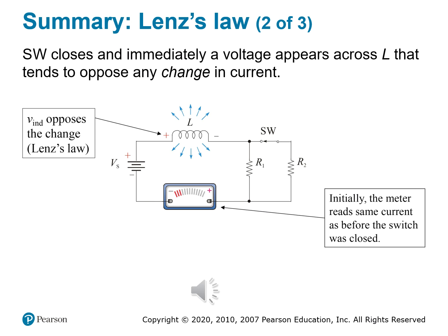The induced voltage opposes the cause of the flux change, and so in this case, the surge in the current. That's why the meter initially reads the same current, even though the circuit path has changed. The current doesn't jump instantly. I'll remind you again, think of it like electrical inertia. A coil wants the current to ramp up slowly. It generates a reverse voltage to delay that increase, and eventually the inductor settles and the current rises, but not without a fight. This behavior explains voltage spikes when you open a coil-driven relay, slowed current rise in power converters, and why inductors help smooth or limit fast transitions.